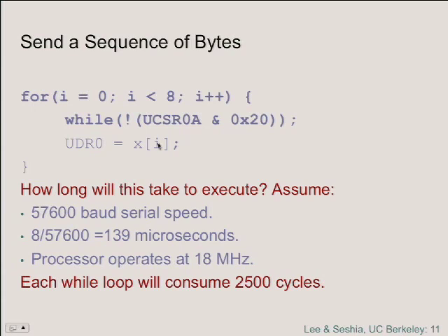So if you have interrupt service routines that are using the serial port, you better make sure to disable interrupts between this while loop and this. Now that could be a problem. Disabling interrupts while you're doing an open-ended while loop means, gee, I could be not responding to the physical world for a long time. Even the reset line is handled by an interrupt. So that could be a problem. You have to think about these things when you're architecting your software.